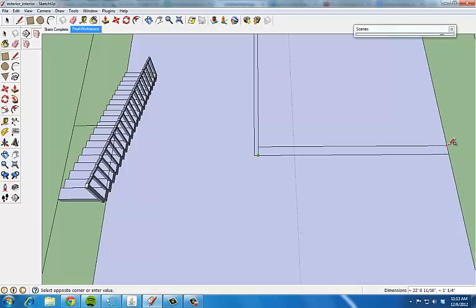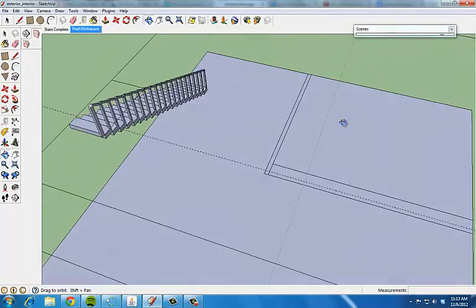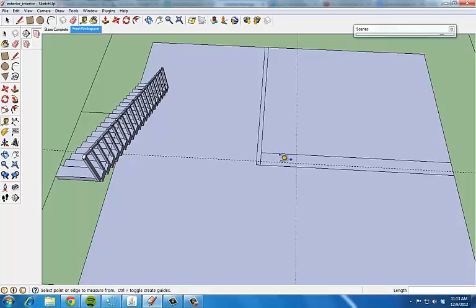It's going to be harder for me to figure out the 6-inch part, which is where my tape measure comes in. I'm going to bring my tape measure into it. I'm going to start on this line, click once. I'm going to move up just straight in the red direction and say I want it to be 6 inches. Click. And that just creates this nice little guideline for me of where 6 inches should be, so I can quickly take this line that I made and move it down to that guideline.